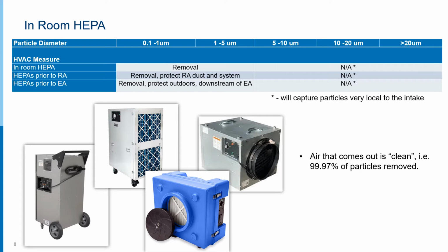Now, there's some misinformation out there about HEPA filters. Since HEPA filters are only rated down to 0.3 micron, I've heard it said that, hey, a 0.1 micron particle could fly right through that, and that is false. There have been tests on that. If you need the analogy, imagine a very small fly trying to fly through a bug screen, and of course, he'll make it through, no problem.